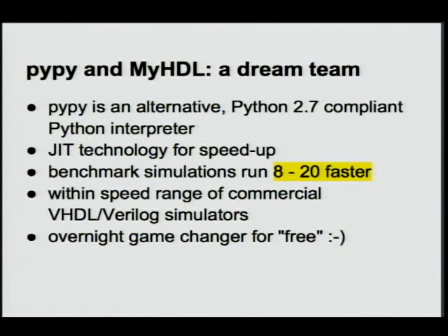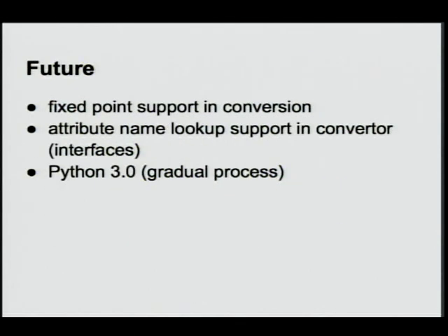With this, just by using a different interpreter, my simulations are now in the range of commercial Verilog and VHDL simulators, which is a rather remarkable result if you think about it. So this was really an overnight game changer, I believe, basically for free. I use it all the time now for lengthy simulations because it makes a real difference. So that was PyPy.